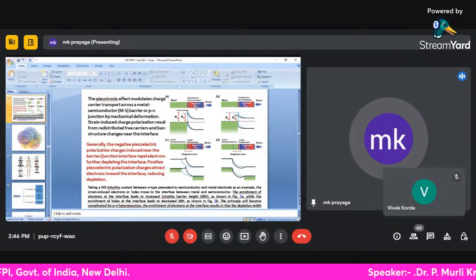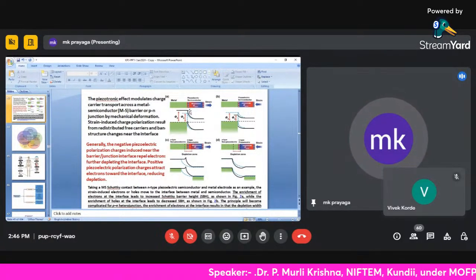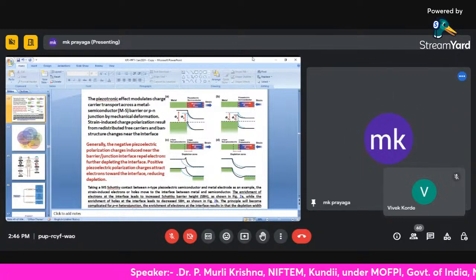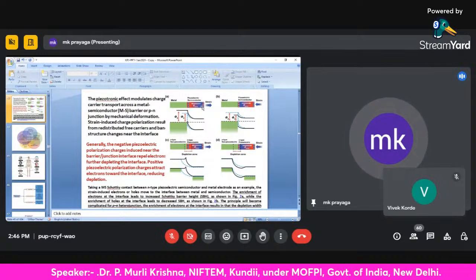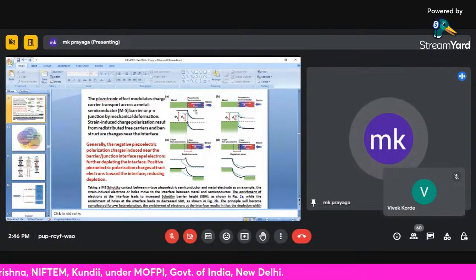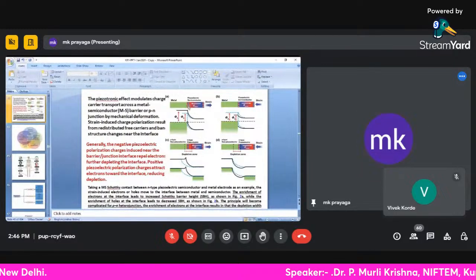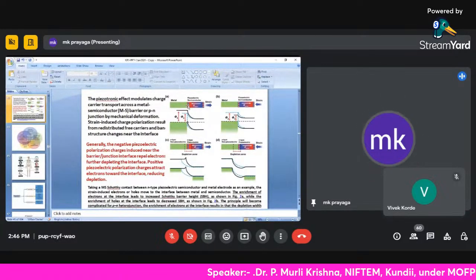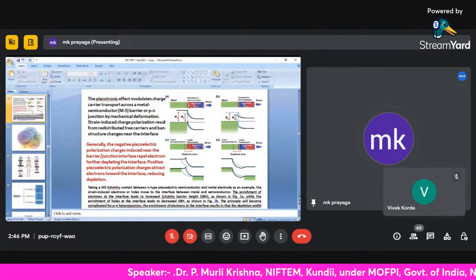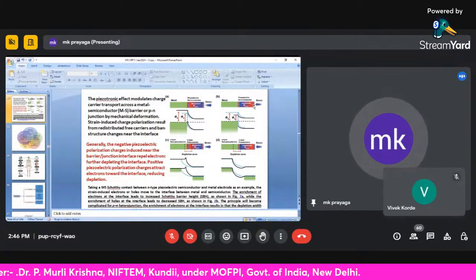So this is a semiconducting piezo material, which is zinc oxide. Studies are majorly reported for zinc oxide only till now, and nowadays people are exploring more materials. Here, strain is applied to the piezoelectric material. The charge is developed at the metal and piezoelectric semiconducting interface, which is the junction barrier location. And of course the stress is applied here, so the charge is displaced.